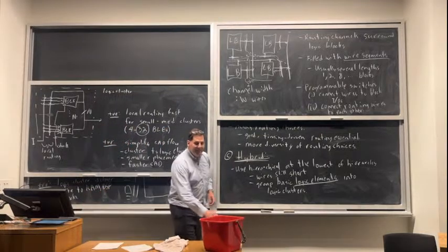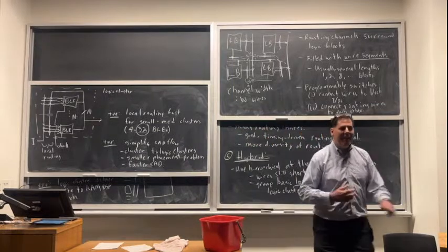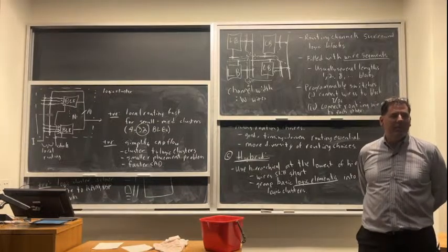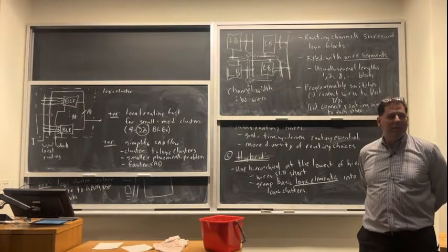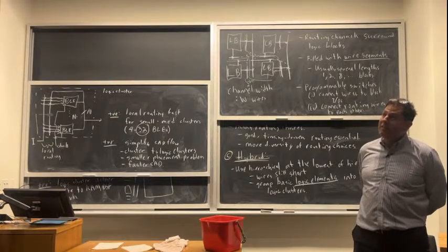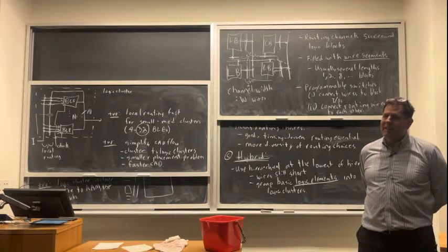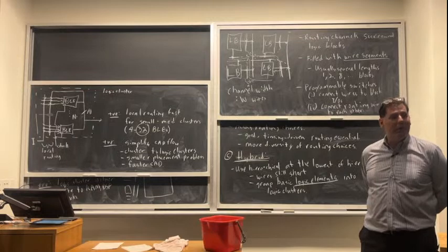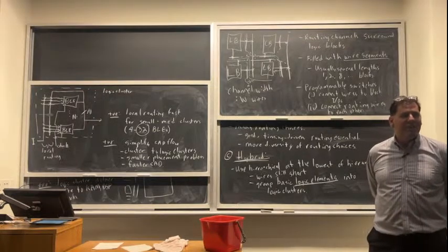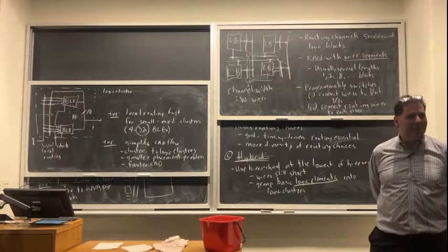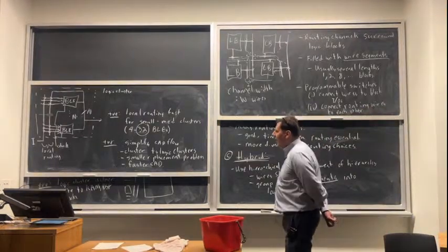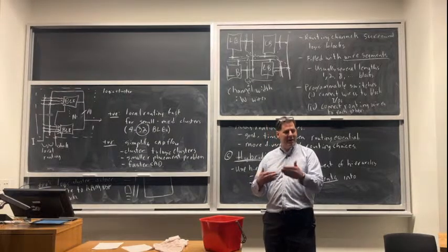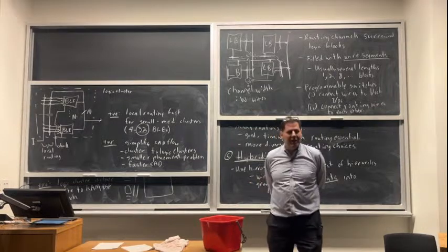Just a random question. With the increasing resistance on the longer length wires, are CAD tools ever leveraging paralleling to cut down on the path signals? Oh, that's a good question. There have been a couple of academic papers that have tried things like that. I think there's one that's tried that. I don't know of any commercial tool that tries it though, because there's a significant power implication and routability implication to that. You'd also need the switch patterns to kind of support it. So I don't know of any tool that is actually doing that.